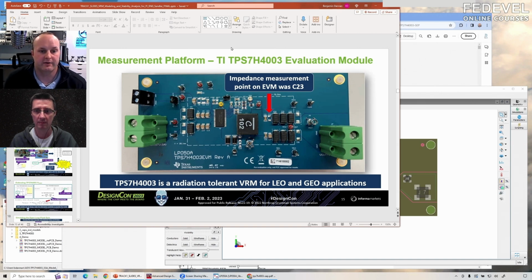And the main reason why I use ADS to do this sort of modeling from a power supply perspective is that, from a power integrity perspective, I care about everything from the load to the power supply or VRM, right? Depending on what field you're in, you might say VRM, voltage regulator module. So theoretically, any simulator can be used.